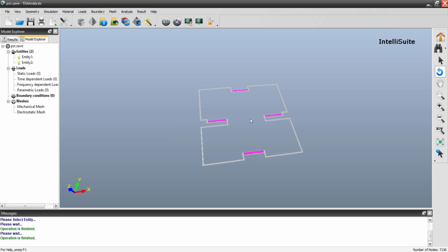So here we had defined piezoresistive material with pi coefficient values. For the metal layer also we had defined 0, 0, 0 for pi coefficients. So this is the advantage here. We can extract even the wire. When we want to do the electrical simulation, even with piezoresistors, even the wire should come in. In case the wire or the metal does not come, then there is no use for electrical simulation.